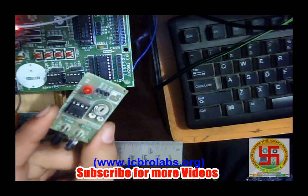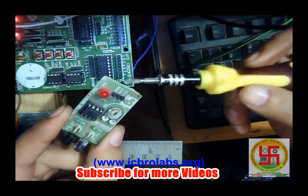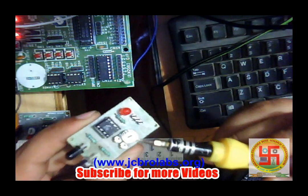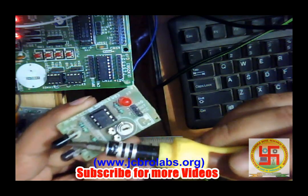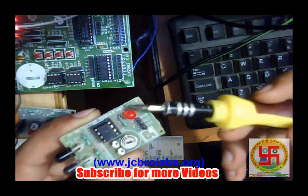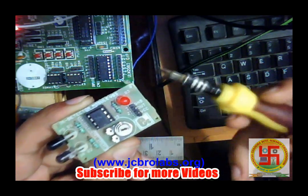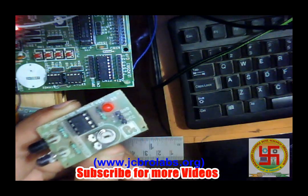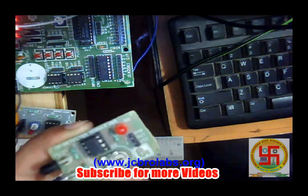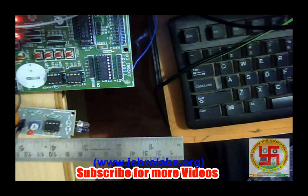So this is the IR sensor, and here we have three inputs: VCC, ground and out, in order to provide the supply. This is the op-amp, this is a variable resistance, and here we have the IR LED and the photodiode connected in place. From here we can get the output. These sensors which give output in 1 and 0 are known as digital sensors. By using this op-amp we have converted it into a digital sensor, so that when an obstacle is there it will give 1, and when an obstacle is not there it will give 0.